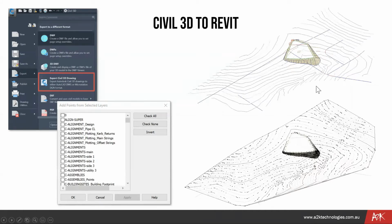So this image in the top right-hand corner is actually an exported Civil 3D file. It contains our elevated contours. You can see there it has existing conditions and it also has a platform that's been modeled. So this gives us some good, accurate information that we can utilize. But the problem is that even though it has that information, it's still very hard to generate an equivalent Revit version of it because of the way that the layers are structured.